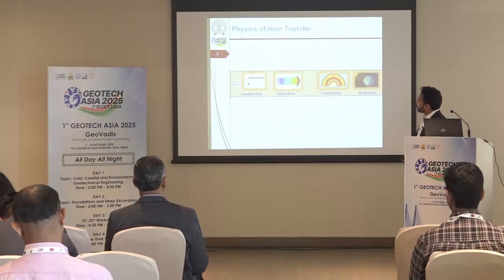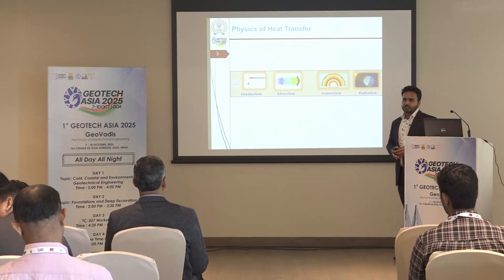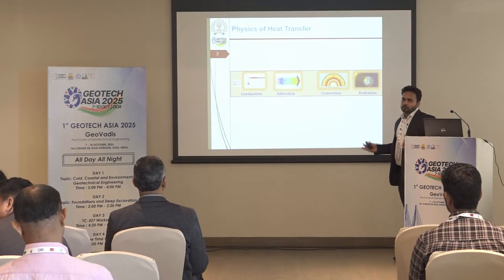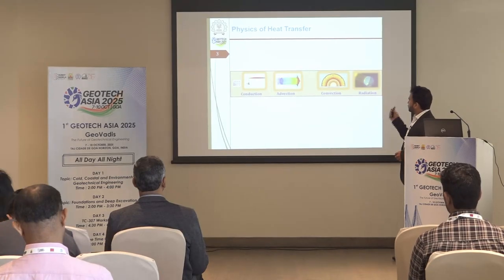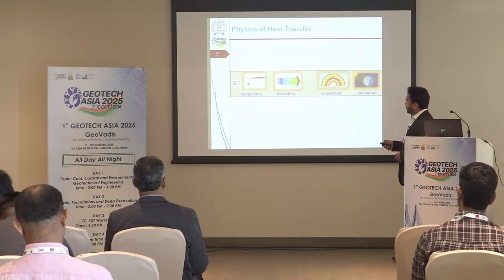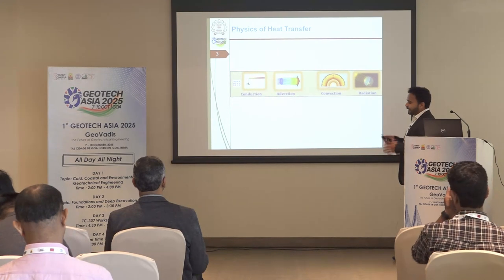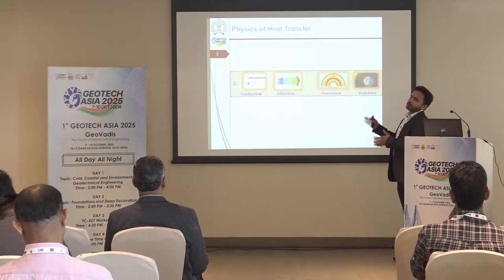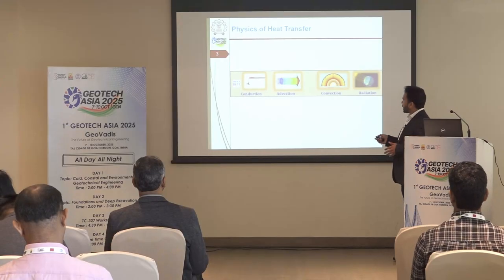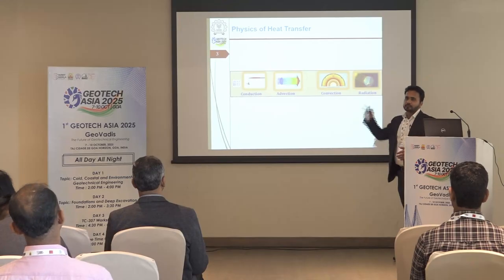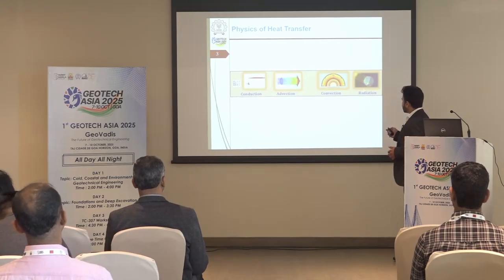So if we talk about heat transfer in the soil, because it's not a core topic in geotechnical engineering, it's important to discuss. We have 4 important modes of heat transfer. Start with conduction, then advection, where heat transfers with the flow of any media like groundwater flow. And then we have convection, where heat transfers within the fluid itself because of the temperature gradient, and radiation, that is not very important in geotechnical engineering.